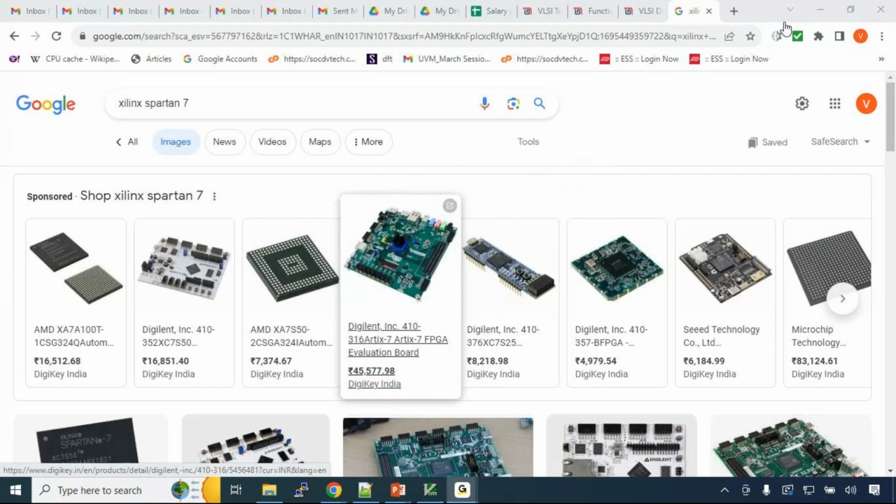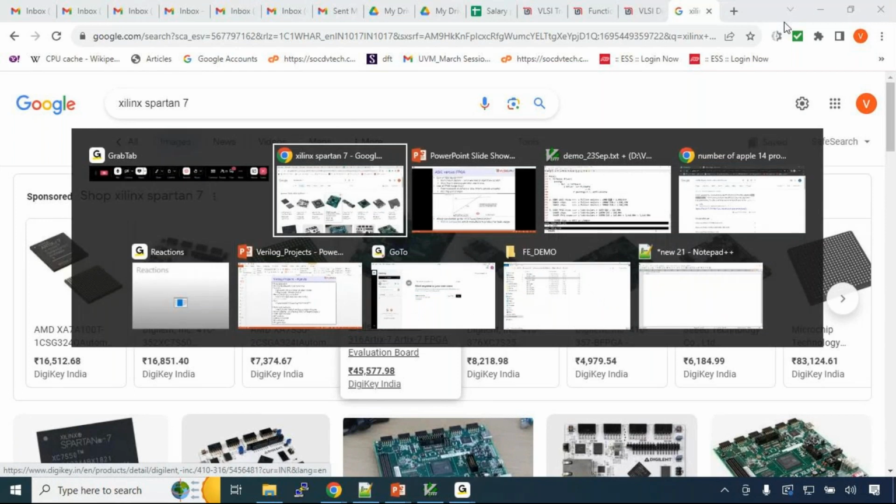Cheaper and more compact. FPGA will be quicker to the market. If you want to release the product quickly into the market, you go for FPGA. But cost will be high. And if there are any issues, you can fix them easily because you just have to throw the board, buy a new board and put in new logic again. In ASIC, it's not like that. Once the chip is manufactured, you cannot change anything. So each of them has its own advantages and disadvantages.